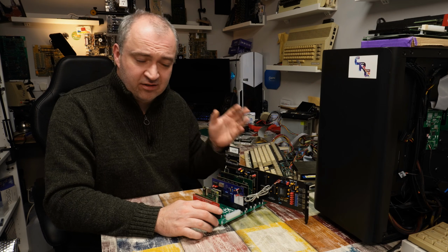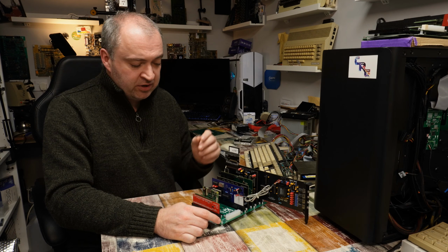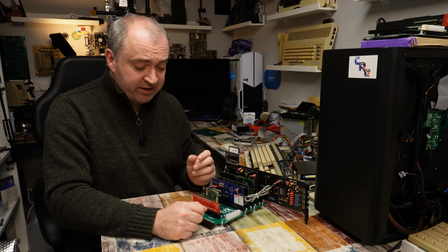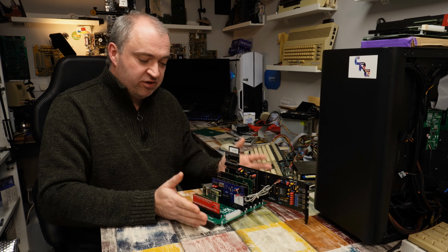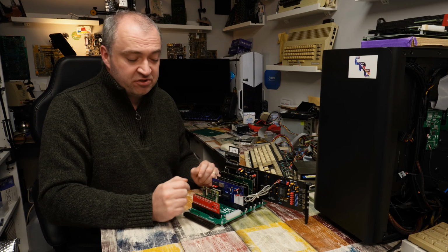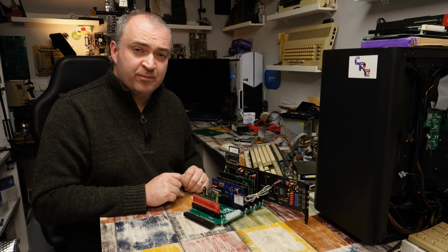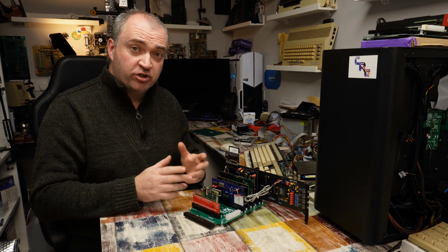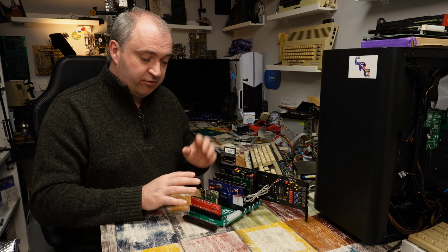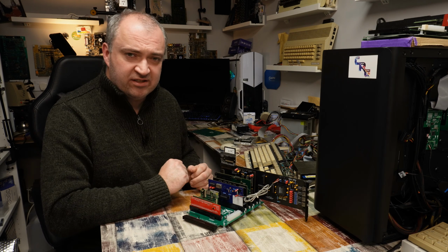Those traces in the 500, in particular the 5V rail, I'm not too worried about 12V or the negative 12V. But that 5V rail is the same size as the others. It looks to be about 1.5mm wide. And I'm just not sure if that could carry enough current to run the A500 without any issues. So if anyone is perhaps more experienced in PCB design, I would love to get your thoughts on that. And indeed your thoughts on anything else that you've seen throughout this build in terms of the board's layout or in terms of the schematics that you've seen there.